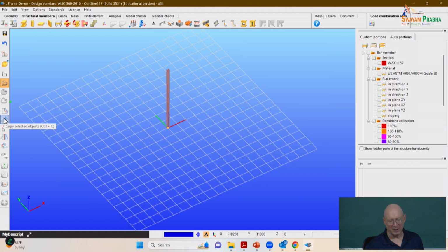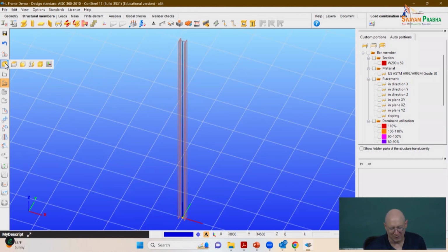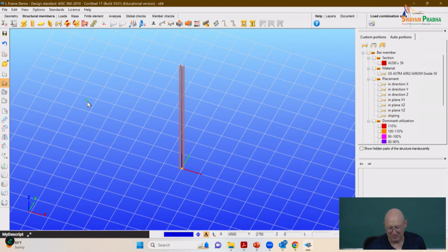So now let's go ahead and do the beam. And I'm going to actually do one thing here. I'm going to set my orientation. Okay. All right, so the beam is actually general. If it's a column, basically it's going to give you a member that's oriented in the Z direction. If you look at the coordinate axes, they're shown in the lower left of the screen. So a column is by default Z. A beam could be any direction. Okay, it doesn't have to be horizontal.